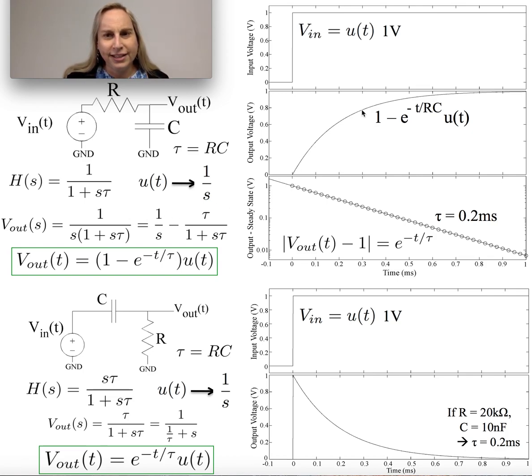But you go, well, that's a nice exponential, but how would I actually figure that out? And I could have done it with either of these curves, but let me do it with this case where I actually will take the output and I'll subtract the steady state from it, which means the steady state is 1. And now I'm actually going to take the absolute value to make sure that I can actually take a log of this. And so I'm actually putting this in log scale. You know, if you're in MATLAB, you're talking about semi-log y or something similar. And you go, okay, what should it look like? Well, if I plotted semi-log y, I would see all my data points, these nice circles. Basically, these are the actual data points at different points down this curve. And notice it's a straight line.